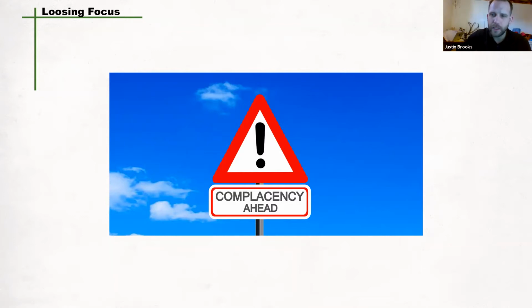Think of the example of the electrician who climbs up and down their ladder several times a day. It's the same task each time, and it's not actually even the main part of their job. So, for example, installing electrical equipment. Having never fallen off the ladder, the electrician may get lulled into a sense of security when the three-point contact on the ladder no longer seems important.